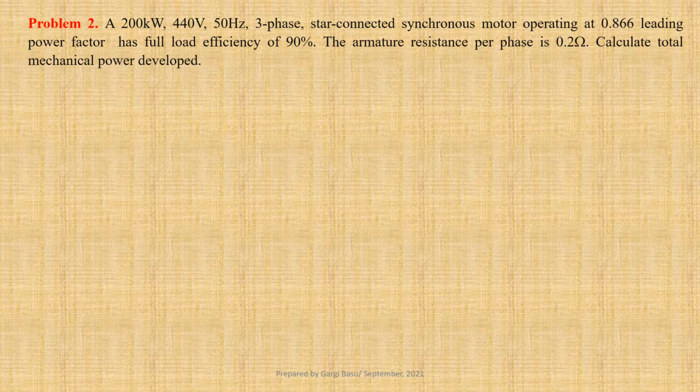A 200 kilowatts, 440 volts, 50 hertz, three-phase star-connected synchronous motor operating at 0.866 leading power factor has full load efficiency of 90%. The armature resistance per phase is 0.2 ohm. We have to determine total mechanical power developed.